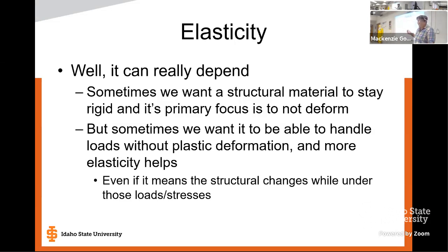But even then, we go between several hundred degrees Celsius and shut down where it might be room temperature, right? So all of our metals are going to have some cyclical lengthening and contracting just due to heat, right? So in a lot of spaces, if we want to ever be able to shut down our reactor and not have to buy a bunch of energy to keep everything hot, which sometimes we do. Sometimes we keep things hot even if we're shut down, if we're going to be shut down for a short amount of time, to avoid cycling.